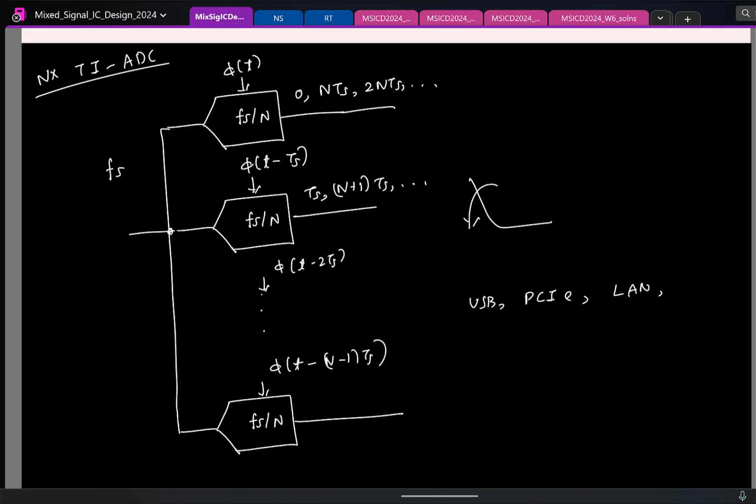There is an analog mixed signal coming there. You are transmitting ones and zeros, agreed, but let us say this is the transmitter and receiver. You are connecting the transmitter and receiver for transmitting at really high speeds. This is not a short circuit. This will have a distributed R, L, C, everything. You will have a whole bunch of things operating. So finally, you need a dedicated transmitter and a dedicated receiver here at the peripherals. Only then can you make this data transfer possible.